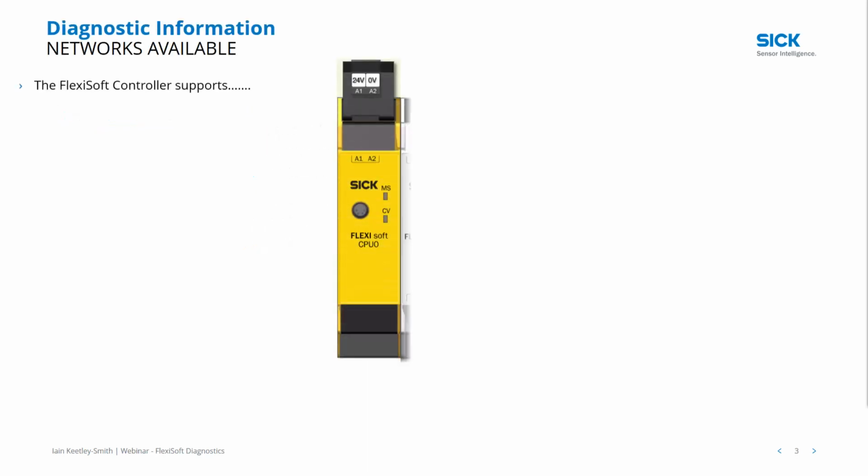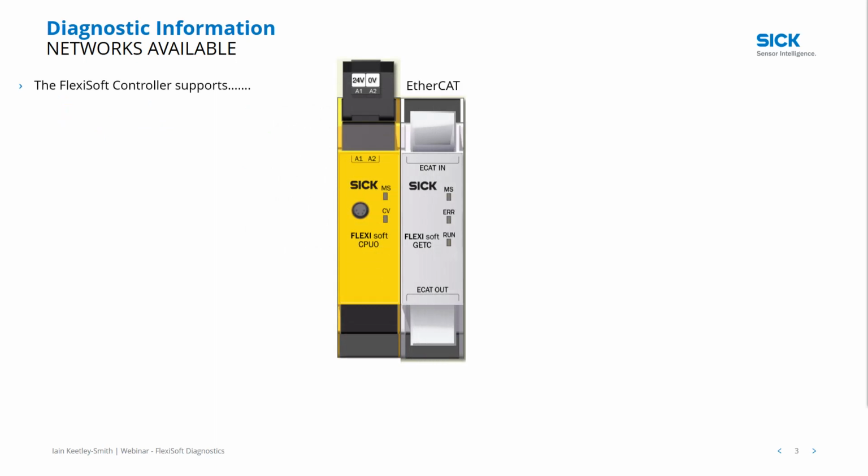So looking at networks available, here we have an image of a FlexiSoft CPU. In this case it's a CPU 0, and up at the top there you can see, as I'm highlighting with the cursor, the memory plug. So this memory plug here holds all of the configuration data. This simply pulls out, and when you push it back in, then the power that's on here on A1, A2 powers up the internal electronics within the CPU, and it also powers up the back plane which connects all of the devices together. So the first gateway that is available to us is EtherCAT.